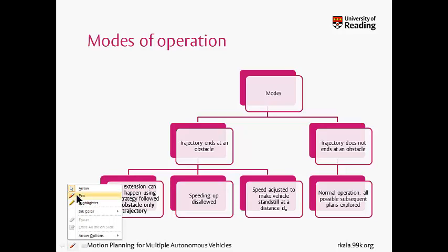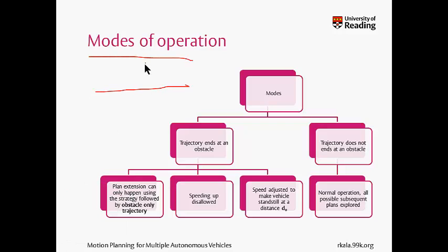The top part of that figure, I need to be, as I said, very wary of scenarios like this where there's an obstacle out here and I come very close to it, because of which I always said that I will be maintaining a trajectory known as tau obs, known as my obstacle only trajectory, which is computed only considering the moving vehicles and nothing else. So that is one thing that I will always be considering and maintaining.